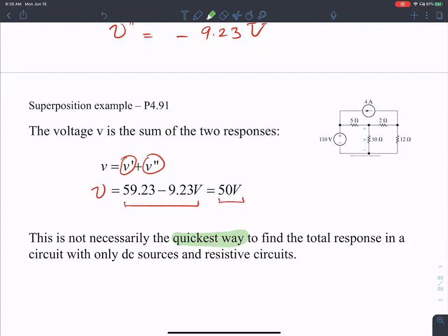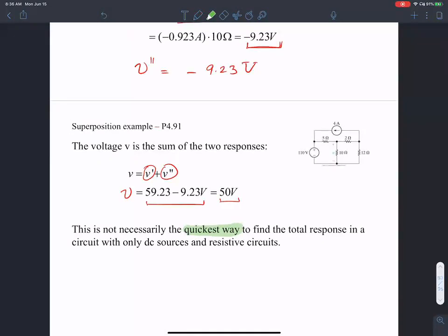When finding R Thevenin, something in the chat from Tyler: when finding R Thevenin in the previous problem, are the 150 ohm and 30 ohm resistances only considered in parallel because they're acting as if the voltage source is in there when finding R Thevenin? Yes.